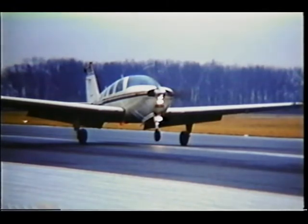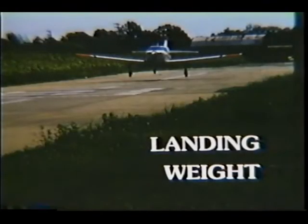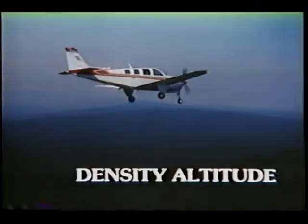All right, time's up. Let's see how many you thought of. Now, I'm sure all of you thought of landing speed. And most of you probably said landing weight. That's very good. You might also have thought of wind. Wind is a very important factor. And another you've probably remembered is density altitude. That's the combination of pressure altitude and temperature. Density altitude isn't as important for landing as it is for takeoffs, but it's a factor all the same.